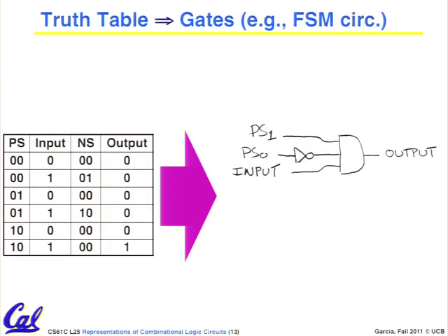So here's another way to think about this. This is the truth table that came out of the finite state machine that we built on Friday to count the 3 ones. Remember there was a 1 here, and that was the only time that your output was a 1, when you were in the second state. You were counting S2. S2 told you that you had seen 2 ones before, and only when you saw another 1 do you go back and output a 1. This is the output as a function of these guys.